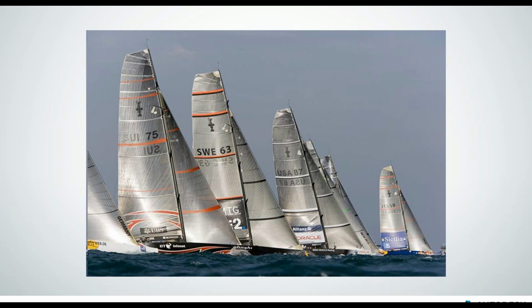And one of the things that I always found fascinating in talking to sail makers, sail designers, is you see these stripes on the sails and you think, oh, they're just logos, things of that sort to just make the boats look really sporty. And no, they're not. The sail designers actually have cameras on the deck of the boat pointed up at the sails, and they use those lines for some of the optics to help identify the sail's shape. And that feedback gets back to the crew to say, this shape is what I designed for these conditions, or no, it's not, and you need to adjust, so that they can get every bit of power and speed out of the sails as possible.